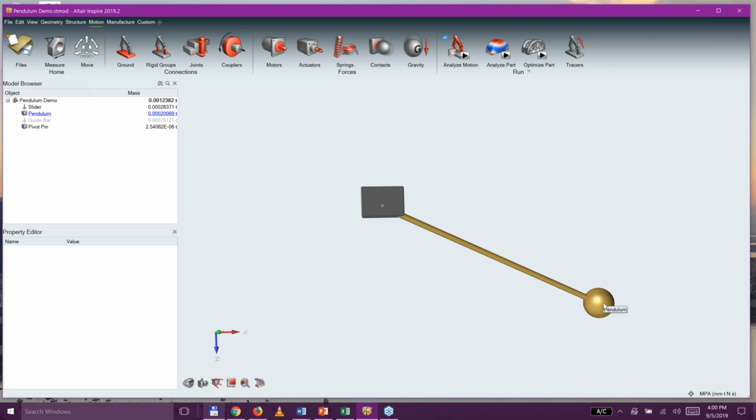They would be free to move separately. So my pendulum could come swinging down, my rod could stop, but the ball, the weight, is just going to continue swinging. And in fact, it wouldn't even swing if I were to do this and set it up properly. My rod should swing like this, and the ball, the weight, would just drop down. So there's some way that I need to connect these together, and there are ways that I can. I can define joints between them, contacts.